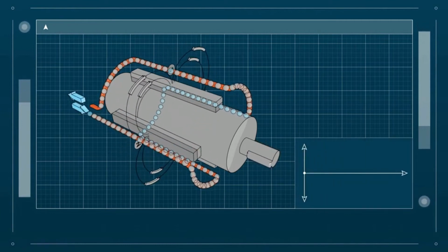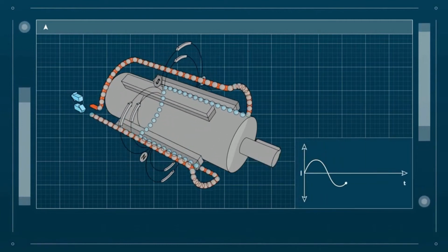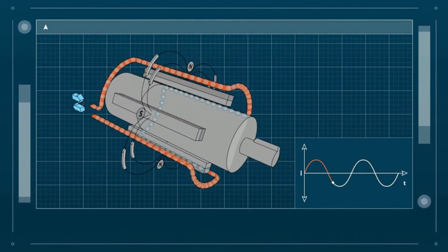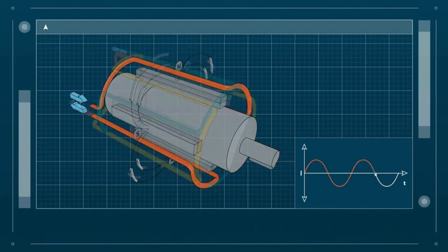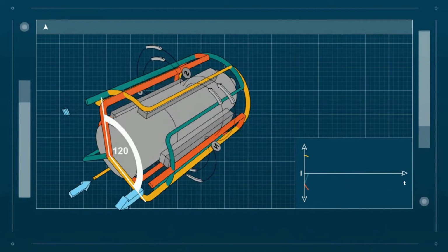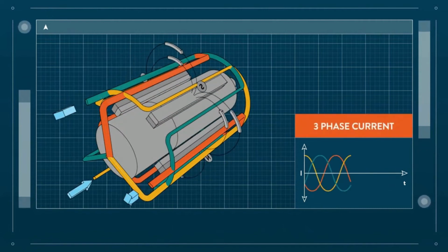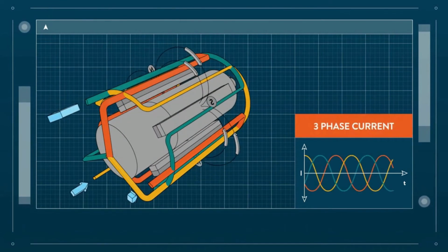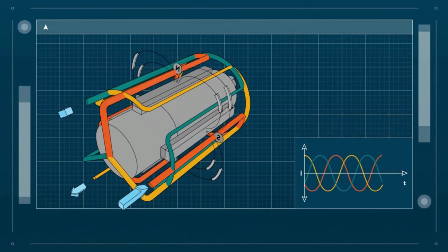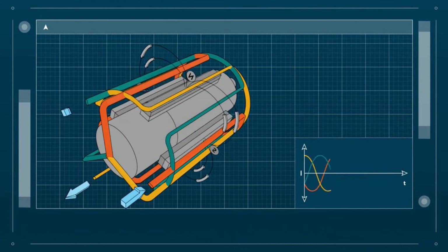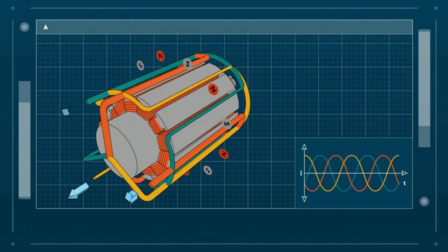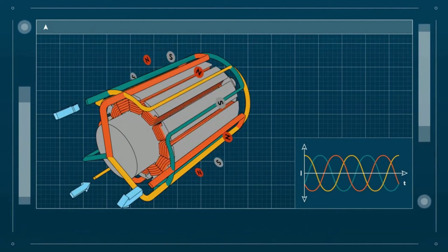direction. The displacement of the electrons during a rotation can be plotted in a graph. This creates a sine wave pattern. Hence the name alternating current. By adding 2 more armature coils at a 120-degree angle, a 3-phase current can be generated. This is generally used for transporting electric power. The speed of the alternating magnetic flux defines the frequency of the current. So, adding more poles and more RPM creates a higher electric frequency.